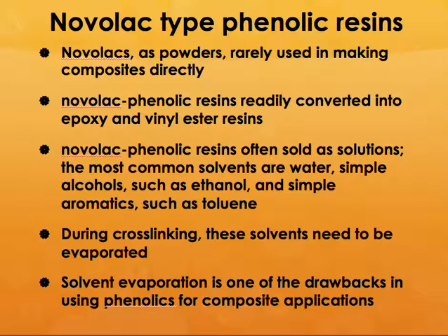During the cross-linking process, these reactants or the solvents need to be evaporated very carefully. So solvent evaporation is one of the main drawbacks of using phenolics in composite applications. If you have a resole type of reaction, the single-step resin system, the water that is formed as well as the solvent that it is in, it is difficult to remove.